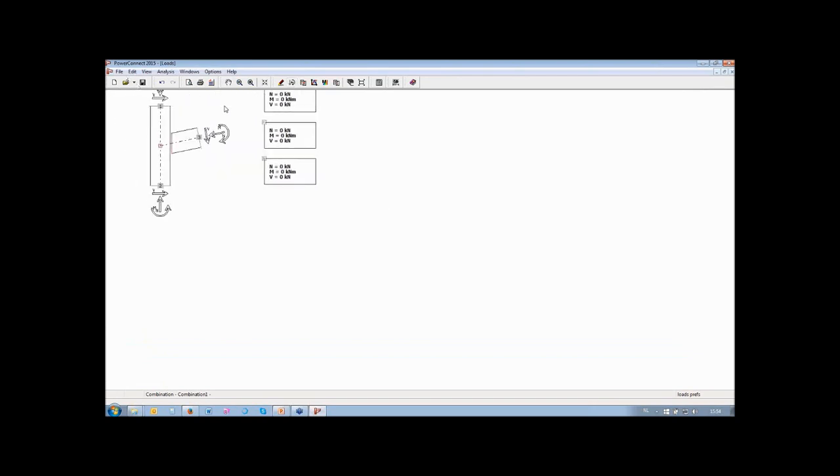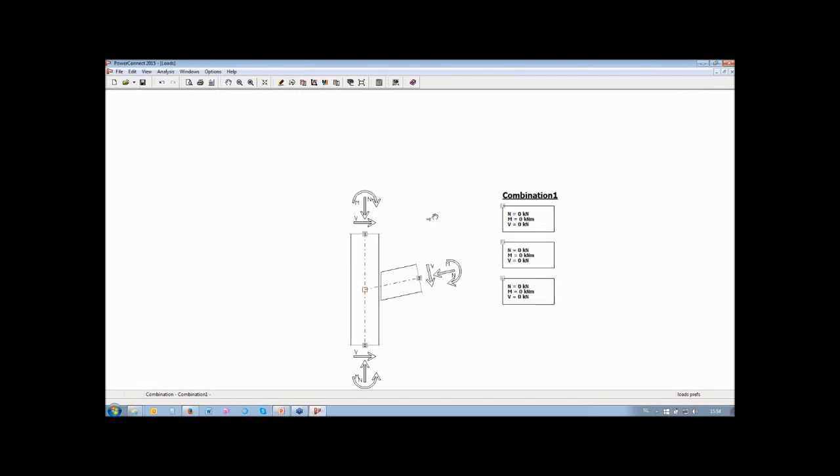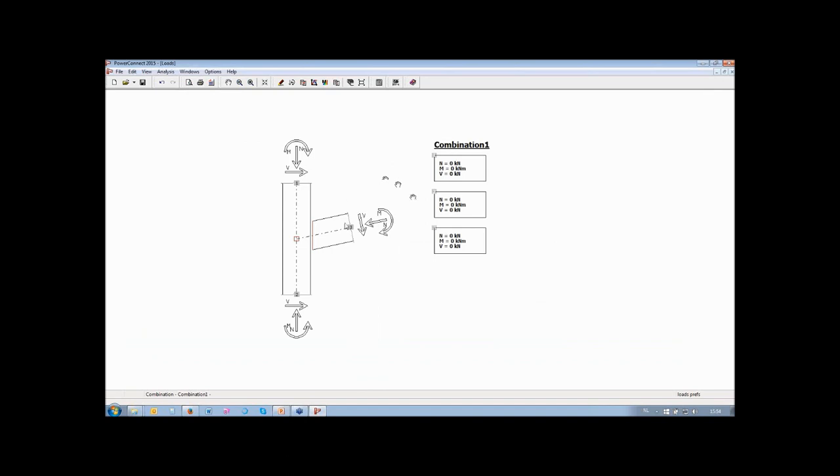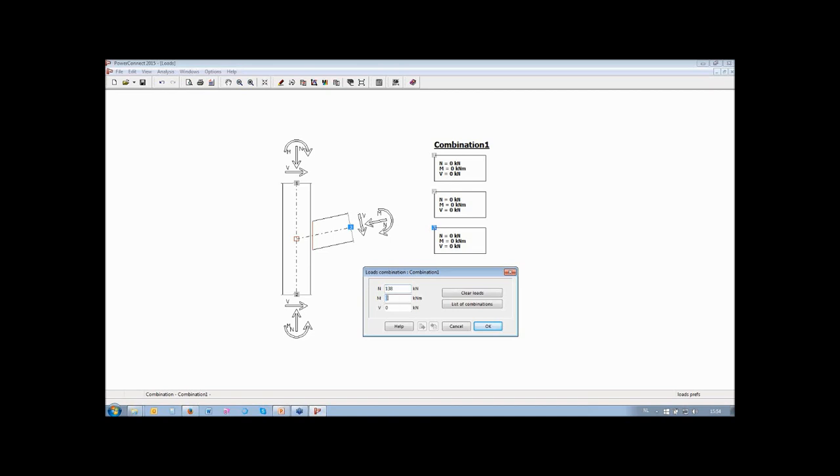Just do a little zoom. Let's place it here in the center. And I'm going to add these loads to the beam, of course. I'm just going to click the little number 3. I'm going to add the loads, which is 138, 200, and 147. Okay. Now, I think it's more than obvious that the current connection will not be able to take on these loads because we only had a bending moment resistance of 84 kilonewton meters, so that won't work with the current connection.